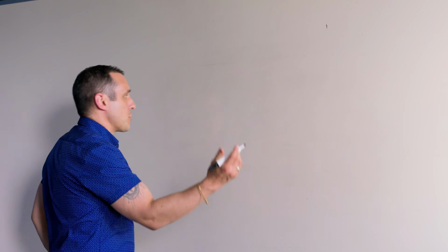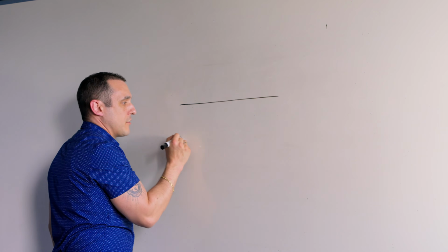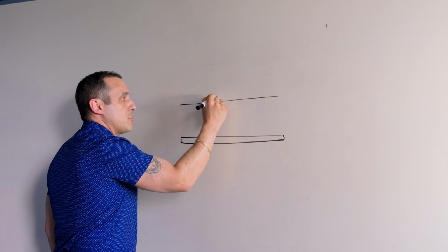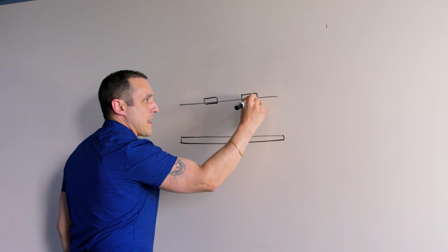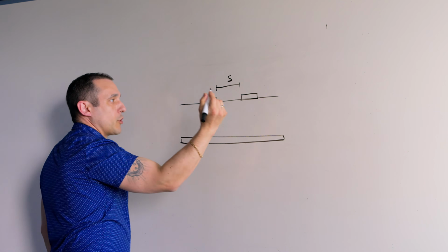So in the previous video that's linked in the description, I did go over all of the fine details of what determines the odd mode impedance in the differential pair. But what I want to do first is just review what happens once we have a differential pair, and then what happens when we add in the length tuning structure. So if you look at, for example, the cross section of a differential pair, we have a plane down here. We have two traces up here. So this is basically microstrips. And then we have some spacing right here, we'll call it S.